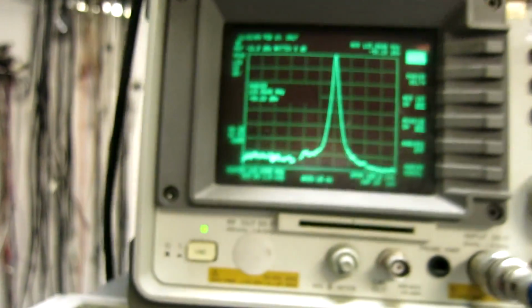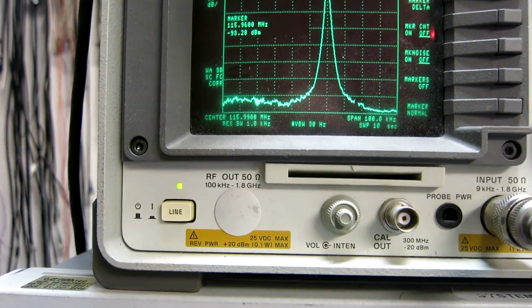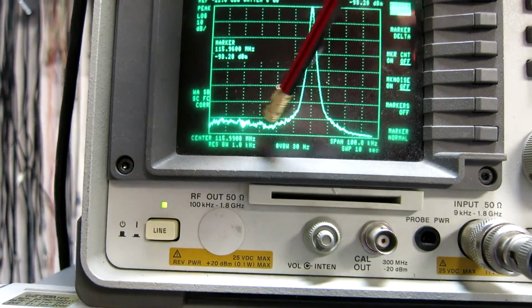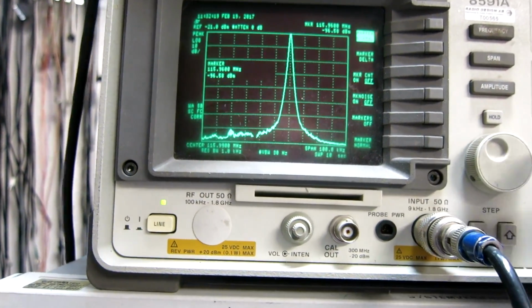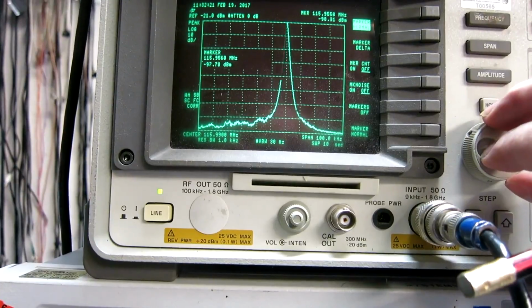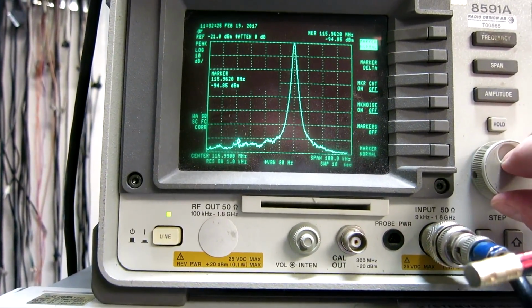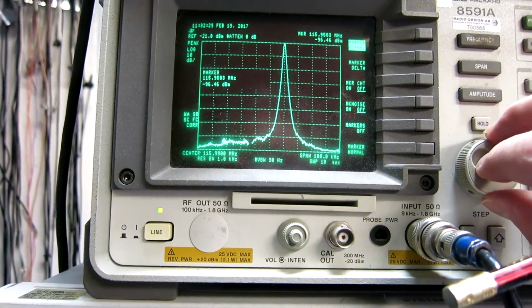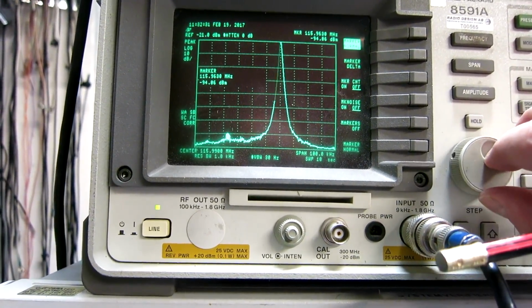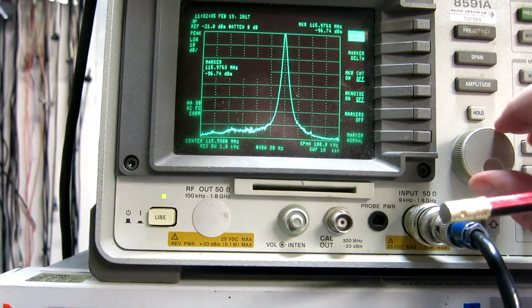Well, look at the spectrum analyzer and the instability of the noise floor here. It can vary. If I turn the marker, you can see down to 98 and up to 94. And I'm looking for the lowest values at some, let's say, 20 kilohertz.